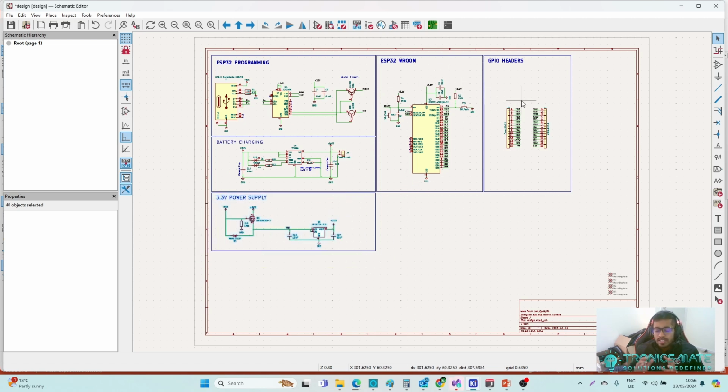So if you are going to design a custom board, and you need to add more things, for example, you want to design a GPS tracker with Wi-Fi, what you can do is add a GPRS module and connect it to these IO pins.